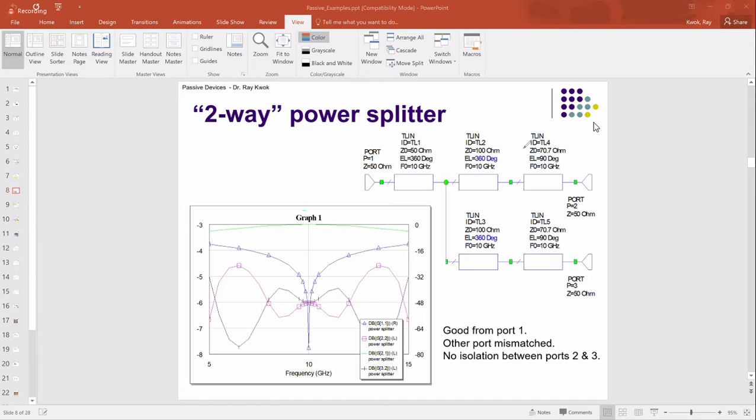I have a quick question. Just like in the real world, what's a good threshold? Is it like minus 30 dB or what? Return loss? Yeah. I'd say it's usually minus 15. Better than minus 15 is good. Typical is 15 to 20.